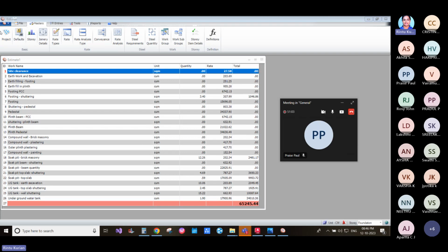Now, this entire set is for fixing parameters. Once the parameters have been fixed, you can go for the scanning part. And before you go for the scanning part, you will have to set the story in which you are working. If you're not going for a foundation story scan initially, change it to the required one. Now I'll be going for the foundation scan and then for each other story.